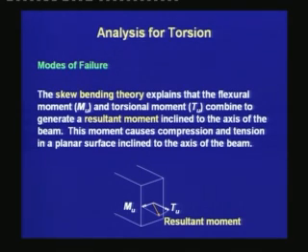The curved failure surface is idealized as a planar surface for the purpose of analysis, and in the planar surface one part is in compression and the other part is in tension. There the action of the reinforcing bars comes into play.